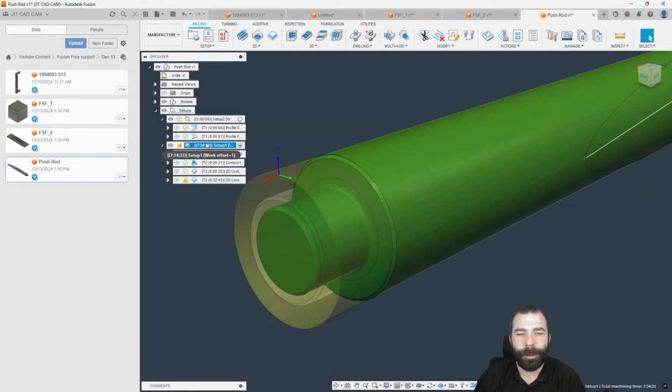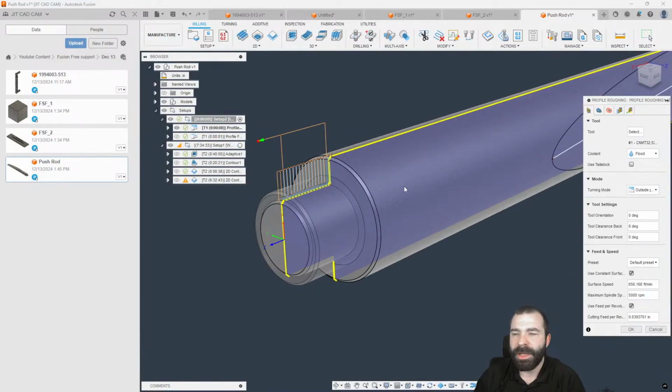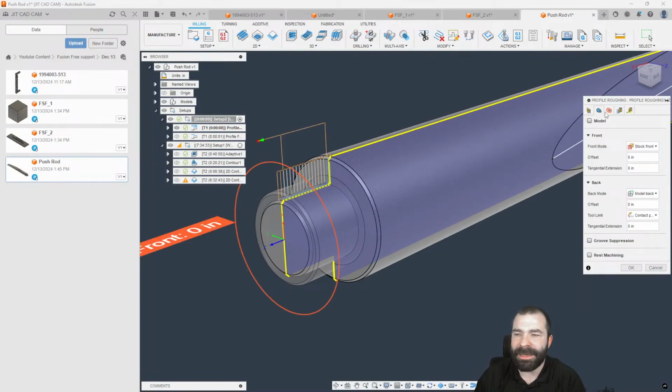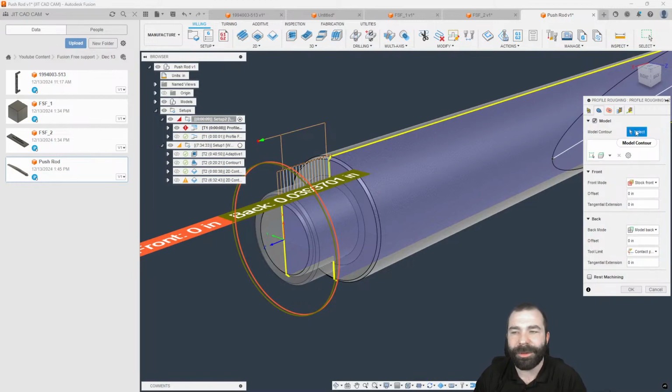Again, in our toolpath for certain operations, we may want to add in that model to be able to manufacture it. Now, in the lathe, the model is based off edge selection. So this is, again, something super cool that you're seeing inside of Fusion, where we're not going to use a solid model, we're going to use a sketched edge.